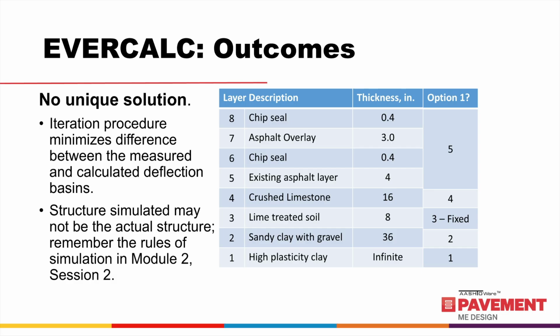Remember, there is no unique solution or set of elastic layer moduli for the back calculation method or iteration process. The iteration process minimizes the tolerance between the changes in the deflection basin and elastic layer moduli, as well as reviewing the root mean squared error.